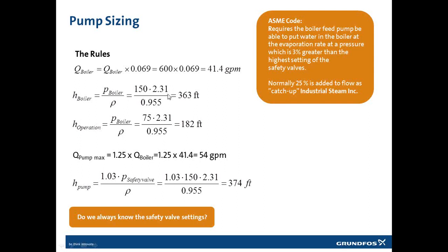That gives me, again, a constant that I need to use, and then I have a correction factor for how much lighter the water gets when I start to heat it. If I had used cold water, I would have had 1 on the lower part of my equation here, but now, because I am dealing with 222 degrees Fahrenheit water, I have a correction factor of 0.955.